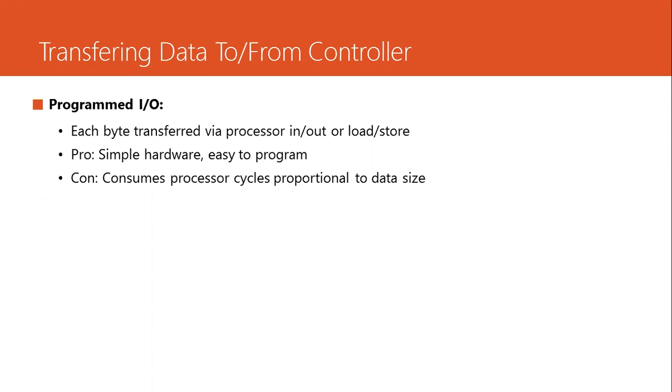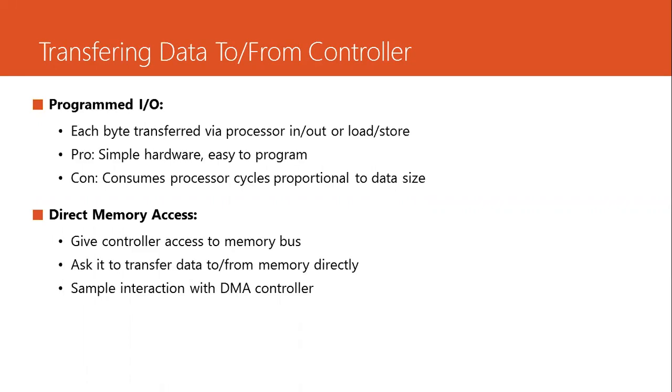It seems a very dumb idea to repeatedly use an operation such as the load in a loop to acquire data from a certain location and not take advantage of dedicated hardware to do that for you, right? So this is basically the concept of direct memory access, DMA, which requests a device to transfer data directly to the DRAM through the DMA controller. The processor tells the DMA when to transfer the data and how much to send. And then the processor gets out of the loop and the device goes ahead and transfers the data, while the processor only finds out through an interrupt from the DMA.